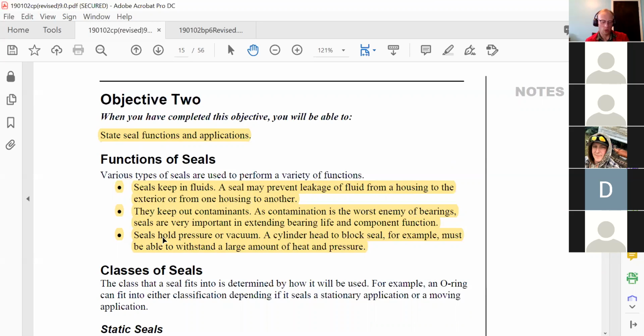Does your wheel seal hold pressure? No, it can't. If you have any pressure buildup in your hubcap or in your hub assembly, the wheel seal is going to blow out for sure. Your diff seal will blow out too, if it's a drive axle, absolutely. In my mind, I was just thinking about a trailer wheel end, just one hub, very small oil reservoir. Oh yeah, nowhere for the pressure to go.